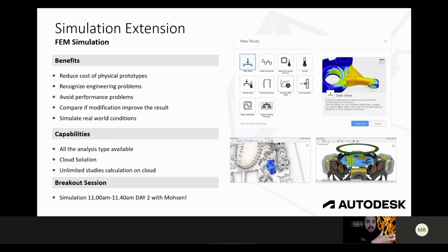You'll be able to simplify and revise your simulation CAD models and then simulate the studies to modify and compare the design changes without the need to export those models. And then finally, you can detect and visualize moldability and predicted part quality of your injection molded plastic parts, and benefit from design change recommendations before finalizing your 3D designs.